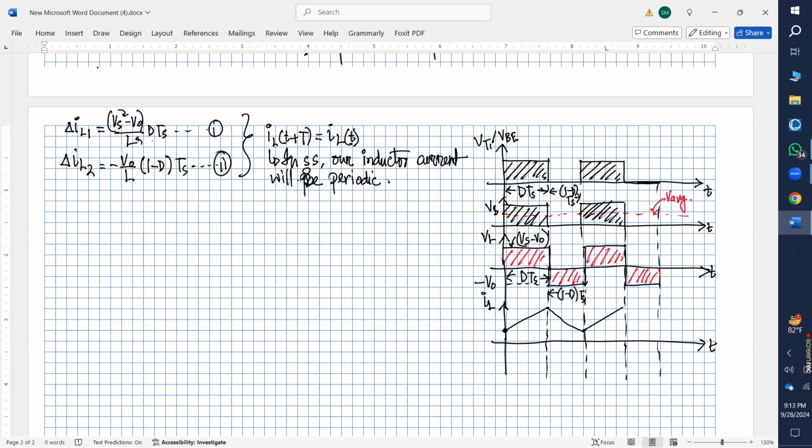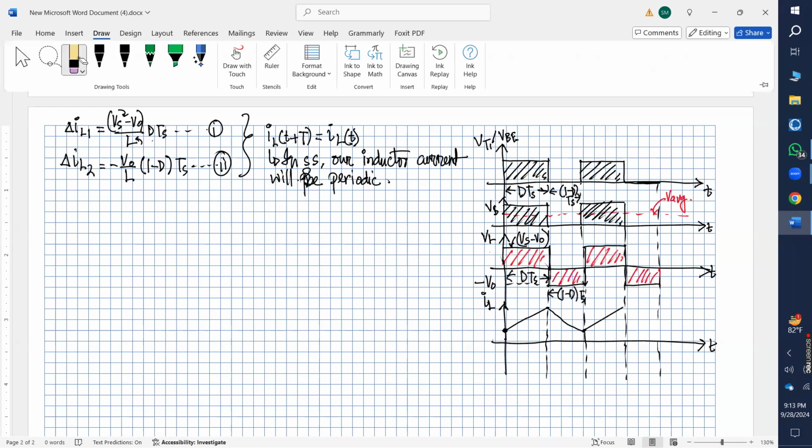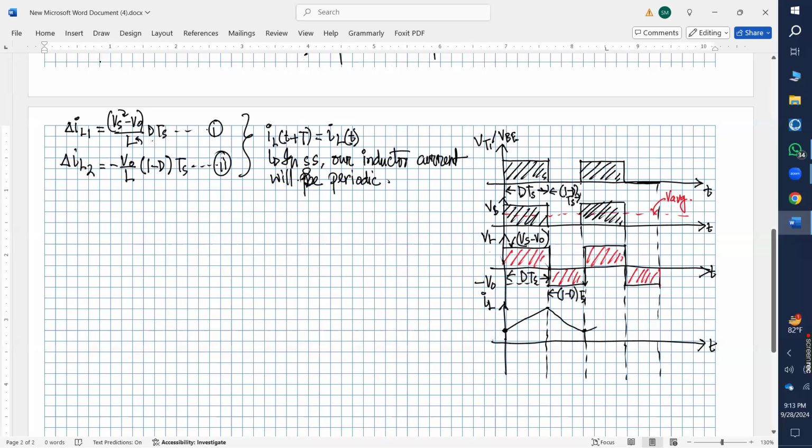So in a similar way, when you get a positive pulse again here, the current through the inductor will charge up, and then again it will discharge like this. The maximum point that we get and the minimum point that we get, we'll define with a name. The maximum point we are considering as IL max, and the minimum point is called IL min. And the total difference here is known as del IL.